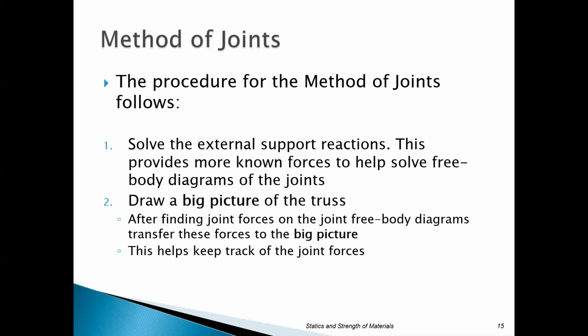You're going to solve the external support reactions first. That's very key. Every problem is going to require you to do that. Okay, that's chapter 3, and that's where we didn't do too well. So if you can't solve support reactions, you will never be able to solve a truss.